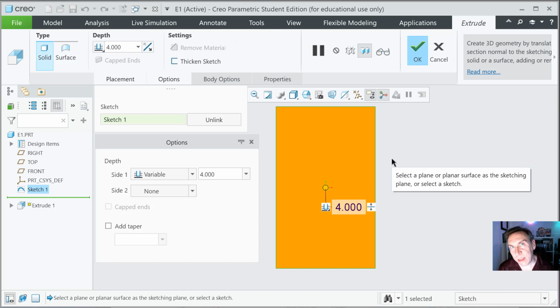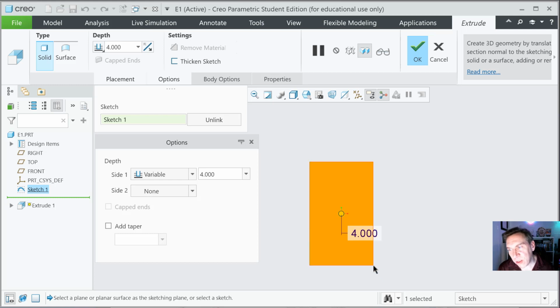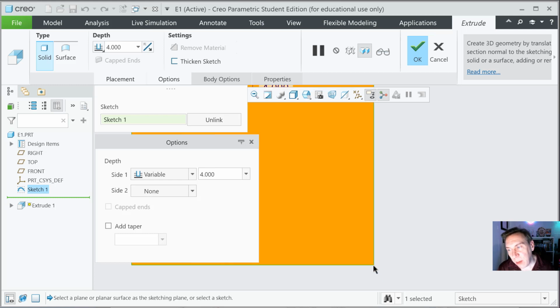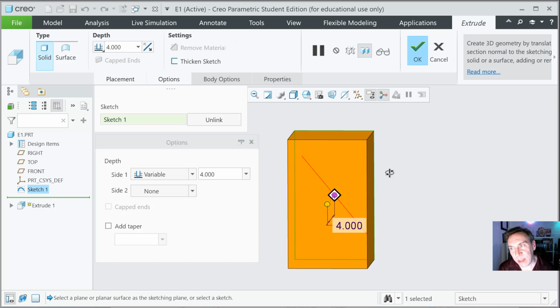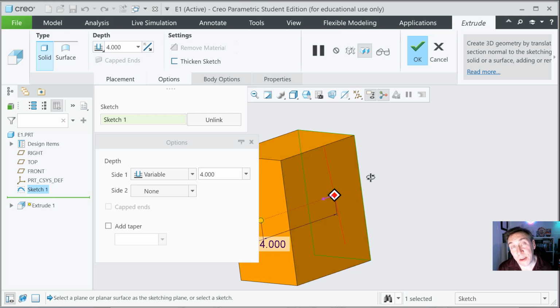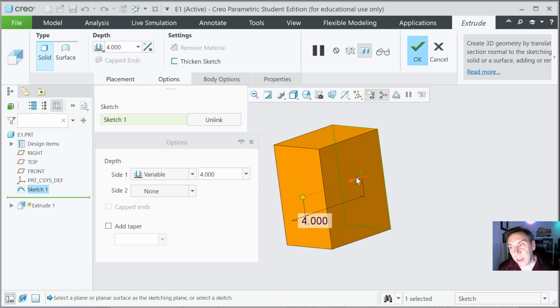Now, to rotate this, hold the wheel on your mouse. Actually, first try scrolling. It zooms in and out, and you could make a focus point. Like, I want to focus in the bottom right corner there. I could keep my pointer fixed on there and keep scrolling, and sure enough, it focuses on it. But if you hold that button down, hold it down like it's a button, the middle wheel, now you could rotate dynamically. And now you could see the direction. This little arrow will flip it backwards or forwards. We want it to go forward.